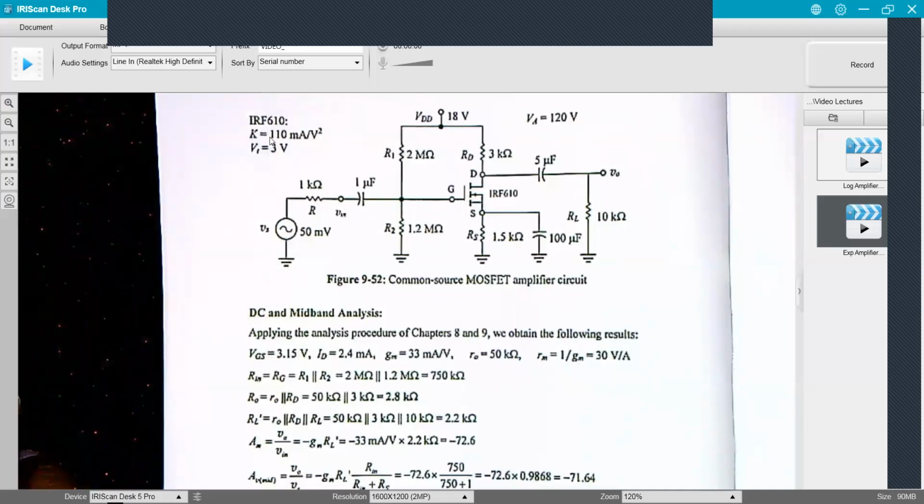There are other MOSFET devices, like the IRF820. They have a different value of K prime. Would that 3 volts change with every different model, or is it constant like that 0.7? No, it will change from transistor to transistor. That's another good question. With the bipolar transistor, it's always a diode junction. This is basically a capacitance, but it depends upon some basically chemistry.